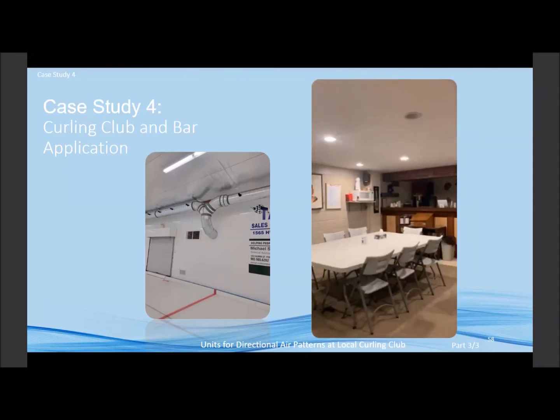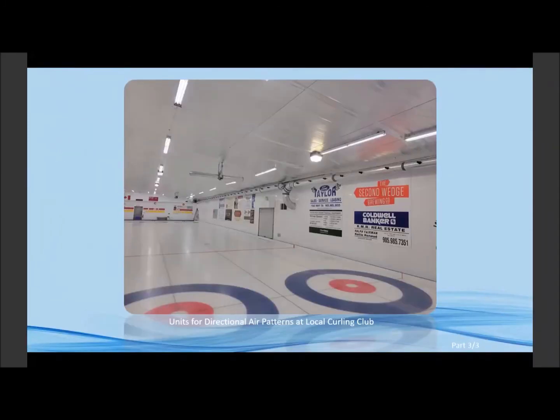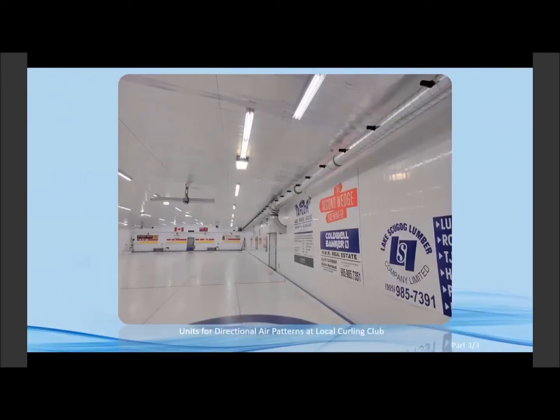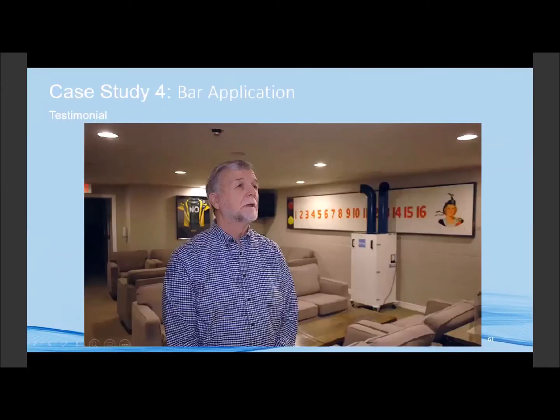And they also had a unit in their bar and conference room. We did this by installing some projection nozzles that were designed to throw the air in a laminar flow 45 feet. It turns out it went about 65 feet without interruption. Obviously, the airspeed slowed down.